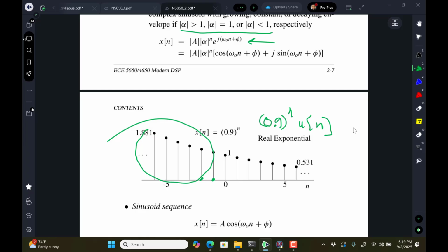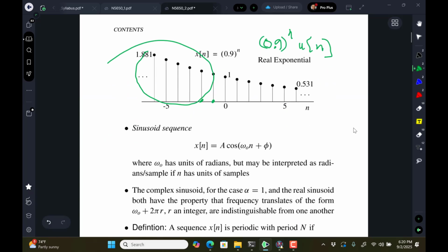And in DSP, you can flip things around a lot more freely than you can in continuous time, because it's just a series of numbers on the computer. You can play all kinds of crazy games with them. You can actually make time go backwards by just starting at your array and accessing it in reverse. Or if you're thinking about processing an image, which would be a two-dimensional array of pixel values, you can do interesting filtering things that are called non-causal operations in a single time axis of processing.